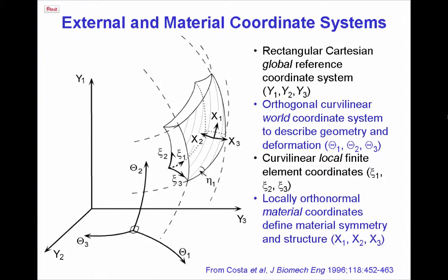The standard predefined material coordinate transformation in Continuity uses the local xi coordinates as intermediates to create a locally orthogonal body coordinate system with one axis aligned with xi1, one in the xi1, xi2 plane, and the third perpendicular to the other two.